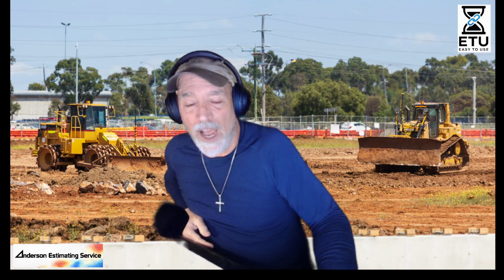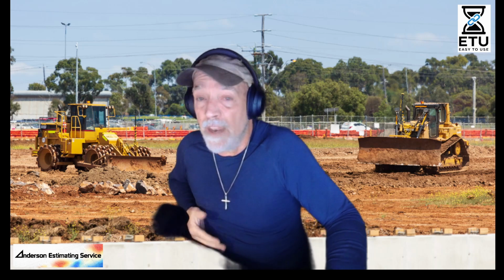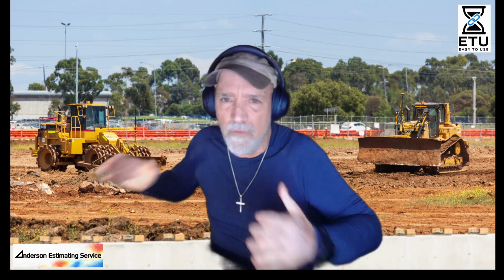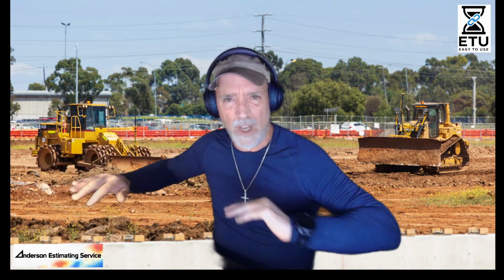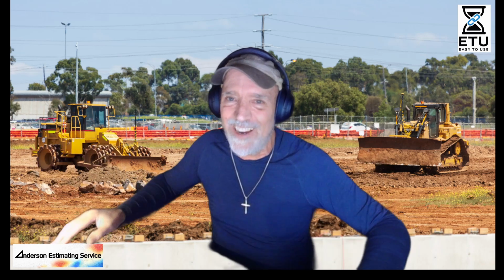Don't overbuild your pads. If you want to do a separate quantity, yeah, there are some quantities you might want to separate. And you know what? Sometimes you might actually have to build that as a select. It's going to be additional select, but you're going to have an offset, because you're going to go out in the parking lot, you're going to leave it low or something like that. So you're always going to try and bring that material on site. You want to move as little dirt as possible and get a good bid. So anyways, that was pretty simple.